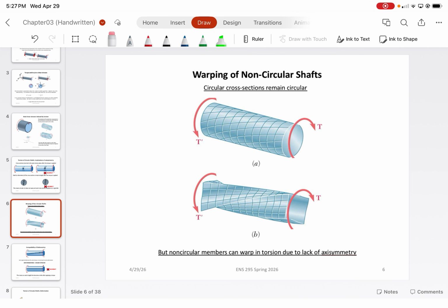Again, we're dealing entirely with just circular cross sections because it makes the calculations a lot easier. Once you start getting into the realm of non-circular cross sections, you get relatively non-uniform stress distributions in certain regions because of warping behavior. This can be seen in the rectangular cross section, where at the corners the shear stresses would actually be 0, because there's a non-uniform stress that increases radially. And that's, again, because of a warping behavior, which is not favorable for calculations.